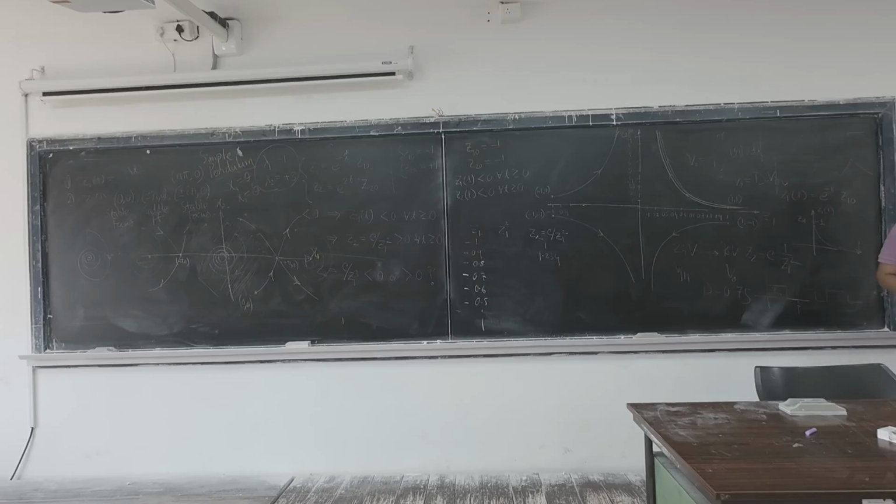When it is T on, you have one specific arrangement with one equilibrium point which is stable. During T off, you have another, because it is a switch, so of course it will be another linear circuit. Both of them would be RLC circuits, which I discussed when we covered variable structure systems. For switch on you have one circuit, for switch off you have another, and the transition happens because you are applying this type of gate pulse to the switch.